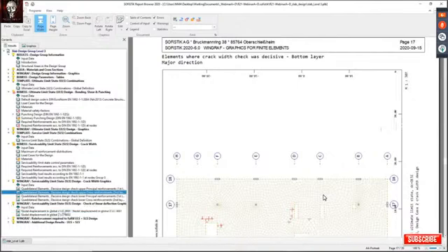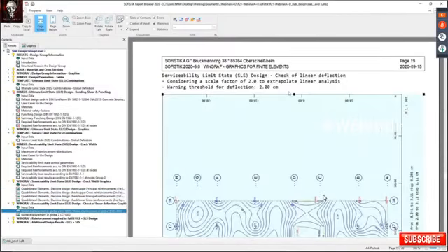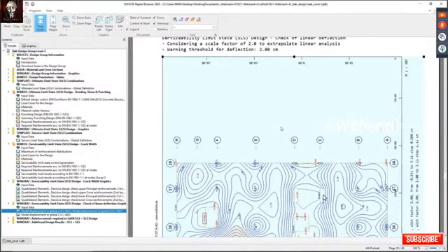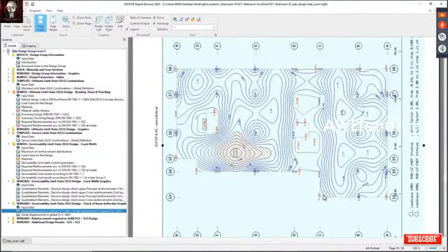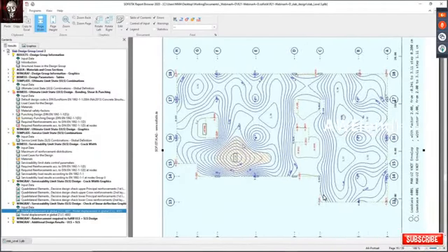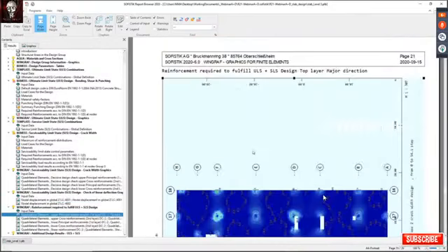As I mentioned earlier, you see now the linear deflection which was extrapolated with the scale factor, and you can see here in orange the part which is exceeding the limit which were defined in the dialogue. So this is very good to maybe see where are the potential problematic areas and decide if you want to do advanced analysis about this slab design, further in SSD, for example.